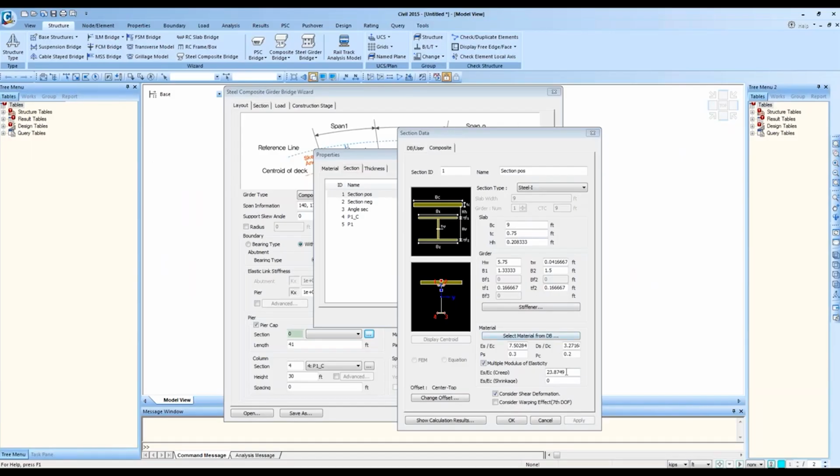But coming back to the program, following methodology B, I would like to use the construction stage analysis and the 3 modular ratio for reflecting the long-term property of the concrete. So based on my n value, I have my 3n. And then I'm going to say, okay, another thing, I forgot to mention this portion.